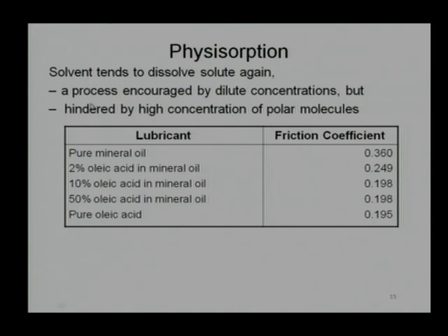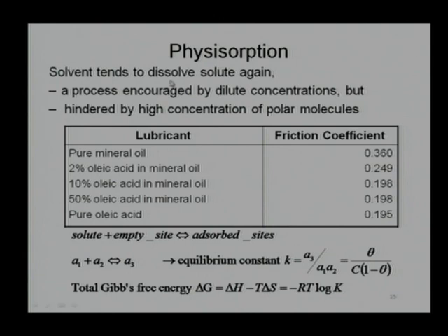Now, removal and attachment with the surface is generally encouraged by dilute concentration. If the concentration is low, then there will be frequent engagement and disengagement of the lubricant additives with the surface. However, if the concentration is increasing, there is a lesser possibility of getting detached from the surface. And often we give this kind of equation, we say that the solute, the mineral oil plus lubricant additives, we are assuming it has some sort of